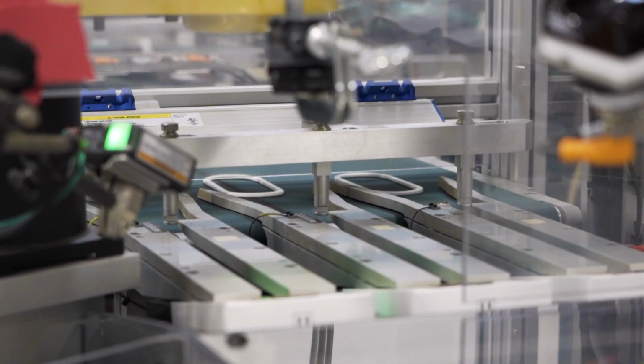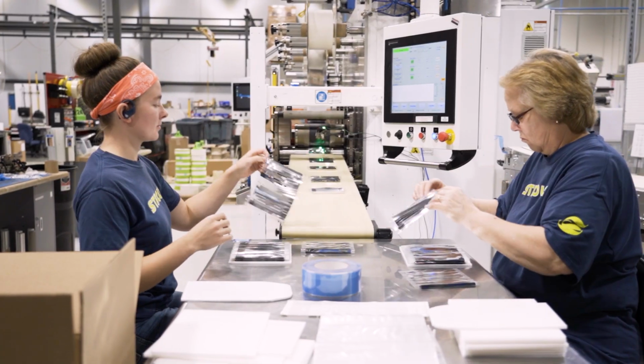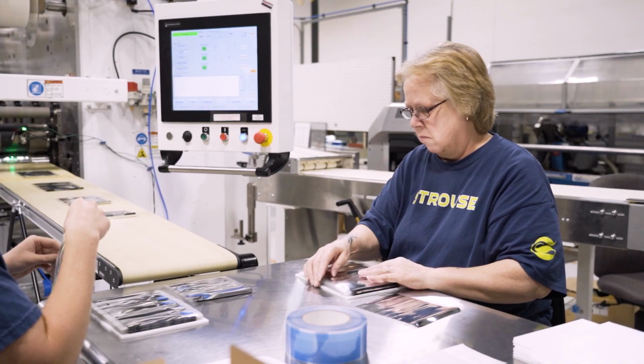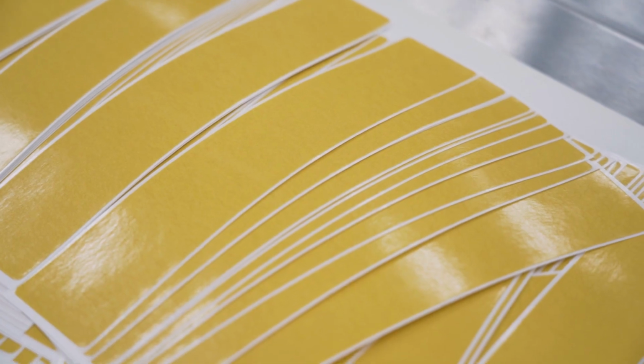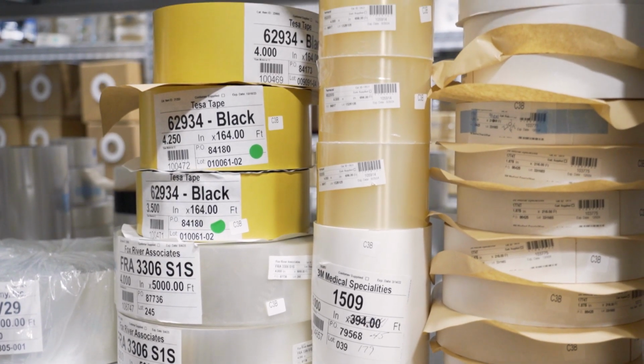Switching from a manual to an automated process can cause problems because automated processes tend to have much tighter tolerances and are driven by sensors and cameras, whereas manual processes are often assembled by hand and can deal with a little bit more variability within the parts. Transitioning between the two processes adds challenges in terms of part consistency, die cut tolerances, and material specifications.